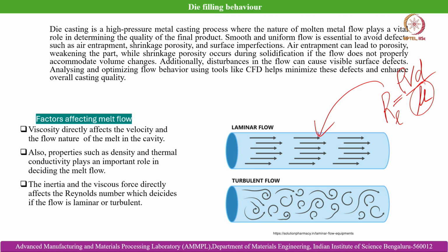And there is another parameter which is not mentioned here, which is the fluidity. Fluidity determines the flowability of the melt, and also its capability to fill a complex contoured engineering component cavity, that is the die. It is related to the temperature, and the solid content if we are talking about semi solid state filling, and also the melt viscosity. If viscosity is higher, then fluidity goes down.